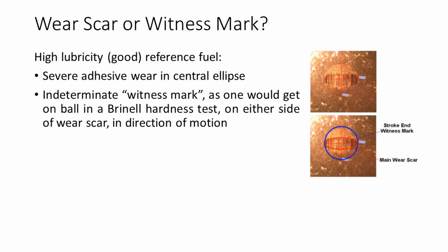One approach is to normalize the nominal scar measurement by dividing it by the calculated initial Hertzian contact area.